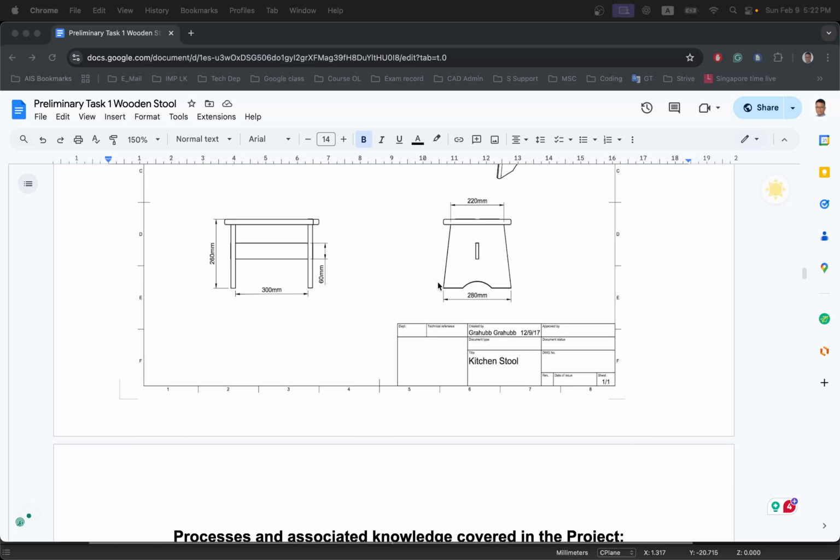You can see in the grid, Rhino always indicates the absolute 0 point with a green and red line. This is the absolute 0. Once you set it here, you can see the piece now aligns horizontally and vertically perfectly at the middle.